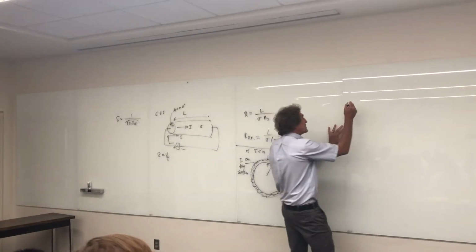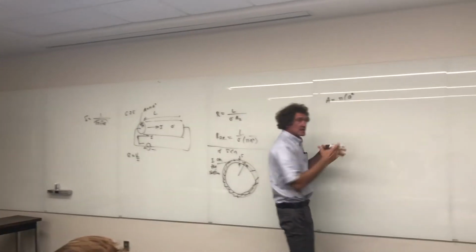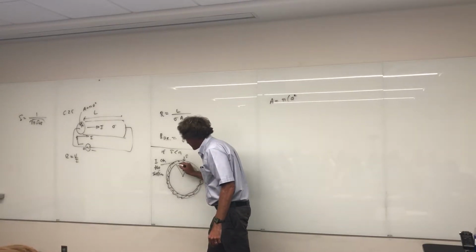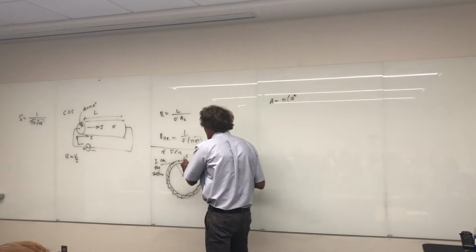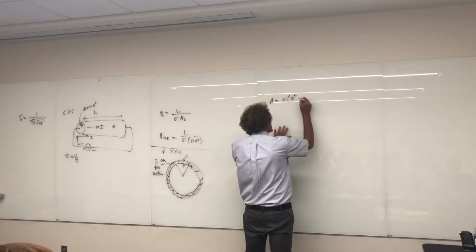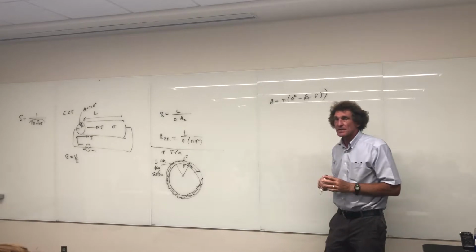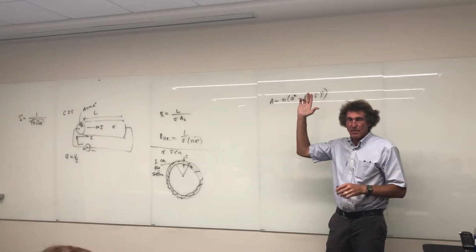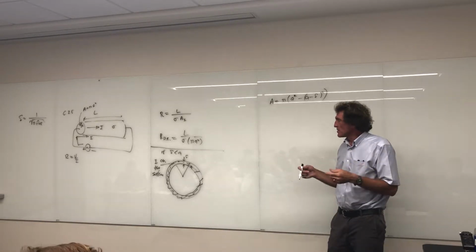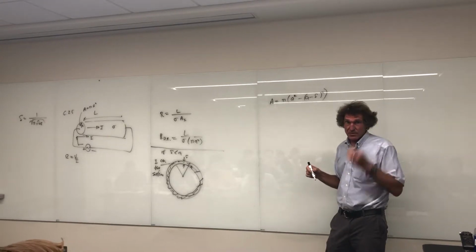The exact definition would be the area of the entire thing, pi A squared. That's the entire cross-sectional area, correct? Then you subtract off the area from here to here in white, which is pi times the quantity A minus the skin depth, squared. So it's minus A minus the skin depth squared. I think I did this last time. How many see this right here? If you think about it, you're subtracting off all that white area from all the area, so whatever remains is where the current flows. Got me?